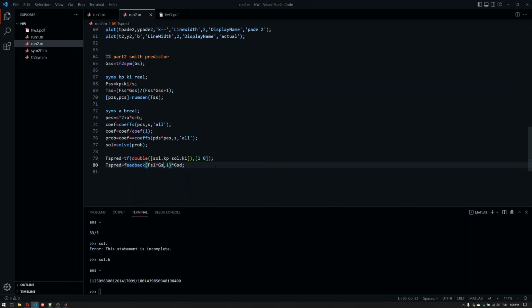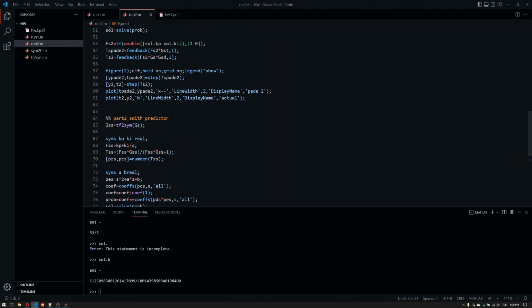So I cannot use the delay transfer function here and then connect my controller to it, because that's not the structure. You have to refer to your lecture notes here, but you should remember that the closed loop will look like the minimum phase part of the open loop times the controller, the whole closed loop of that, times the delay part here.